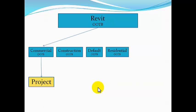So how would it work? So if I start a project straight out of the box using Revit, I need to pick a template. The one that I've been working in here has been the commercial template, and so I use that as my starting point. I have to use a template. I can't just start with a completely blank slate. Even the default template has some content already in it and some system settings and system families.